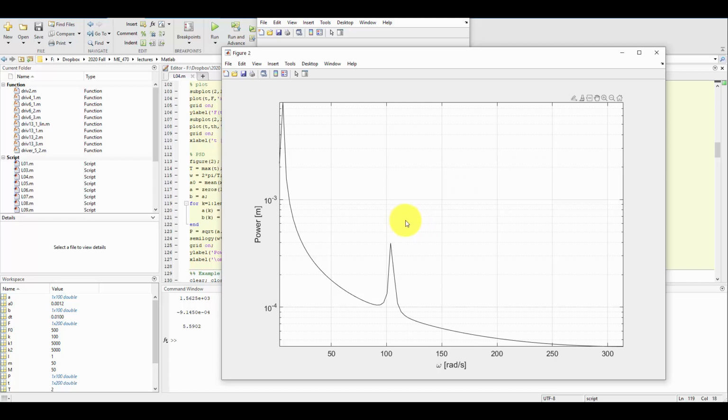And then the range of this that I can detect, that's determined by the time step. I did 0.01 seconds, but I could have changed that here. But I'm pretending like I just collected this data and I'm doing the analysis. So we see here 2 really nice peaks. We see one here at 103.7, and we see the first peak here at 6.283. Now, these are a little bit off from what we expect. We should see 105, since that was the driving frequency, and we see about 104, and the natural frequency was 5.6 about, and we see 6.2.